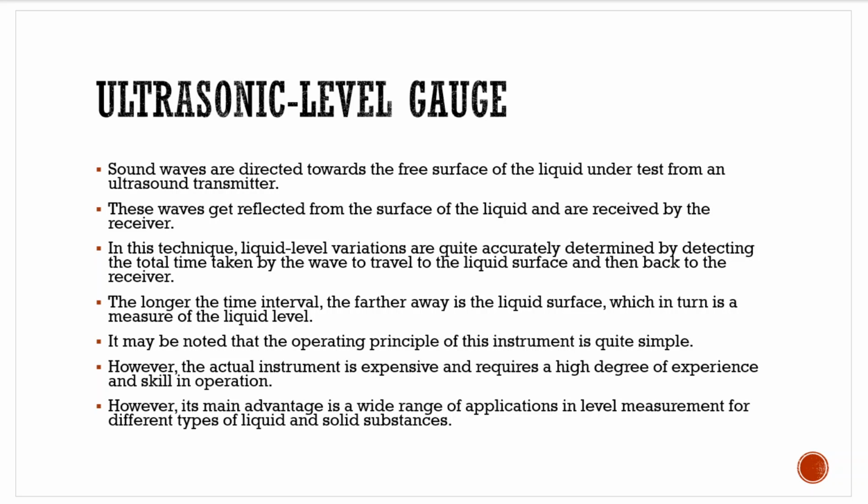vessel in which the liquid is contained, and as soon as ultrasonic waves radiate back from the liquid, they will be received by the receiver. The time taken by this ultrasonic wave to be transmitted and received back by the receiver will give us the level. If the liquid level is low, that means more time will be taken. If the liquid level is high, lesser time will be taken for the propagation, receiving and transmission of these ultrasonic waves.